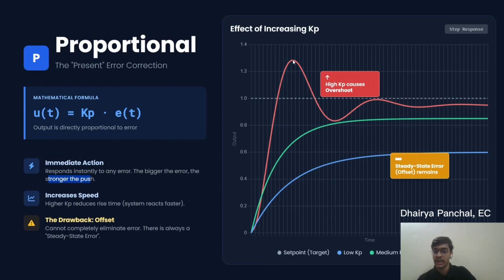And in accordance with that error signal, which is multiplied with your high Kp value, the signal is given an opposite magnitude change. So for this point, your error would be negative as your current value is greater than your preset value. So a correction in the opposite direction is made. So here your system response is reducing to 1.